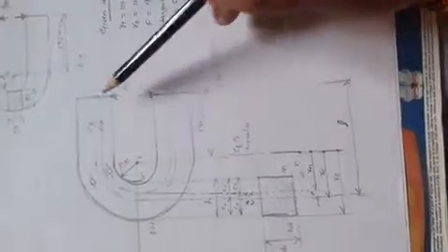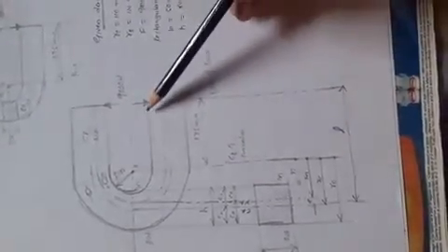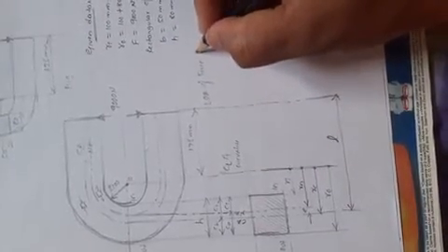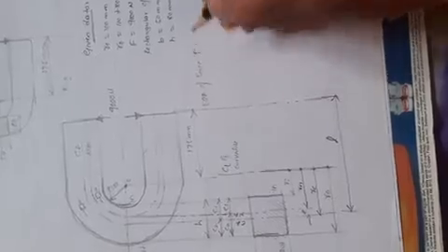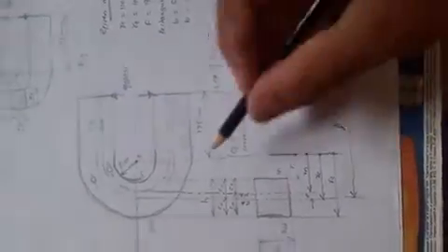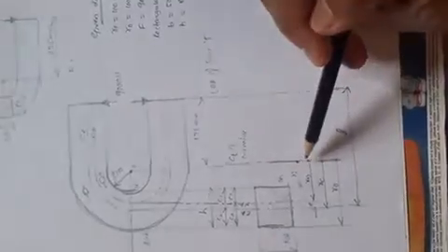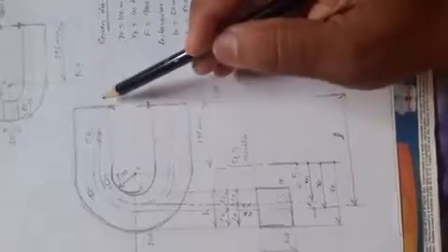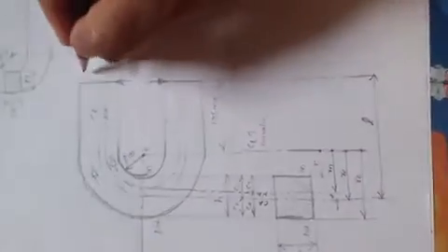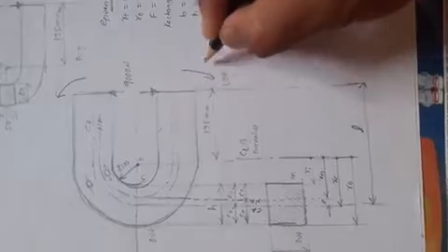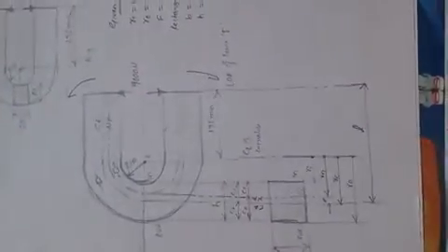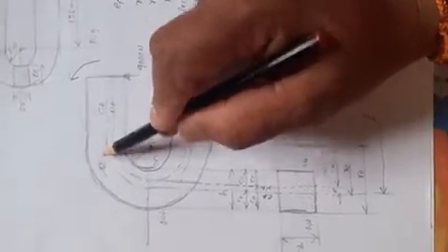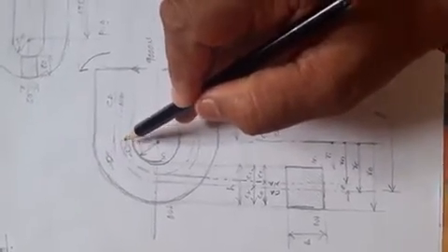Then show that it is subject to a load of 9000 here; this line shows the line of action of force F. This is the center line of curvature, and when it is subject to an external load here, it tries to bend like this. Above the neutral axis, the fiber undergoes compression. Below the neutral axis, the fiber undergoes tension.